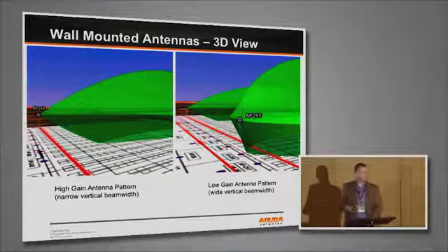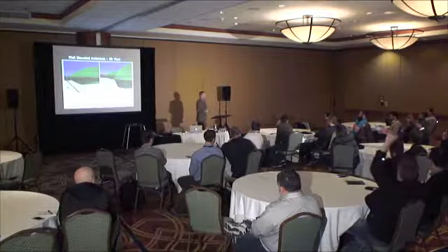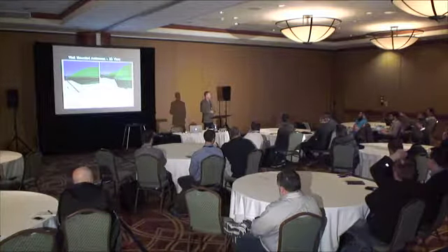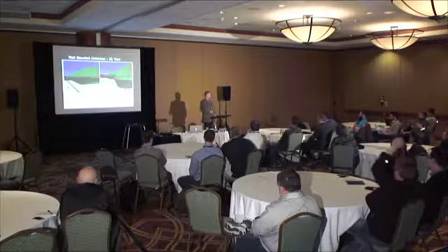Is it likely to be a point where you could get enough mechanical downtime to cover that, but you've got to compromise the other end? I think it ultimately depends on the length of the aisle, right? Potentially you could, but at some point you're down tilting the antenna mechanically, so I'm losing my long range to fill in that shorter area. Whereas if I just went with the 5 dBi or something with a wider beam width, I still cover half the aisle, and I get good coverage up there, and I kind of get both.